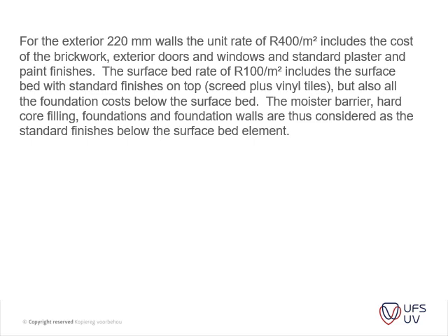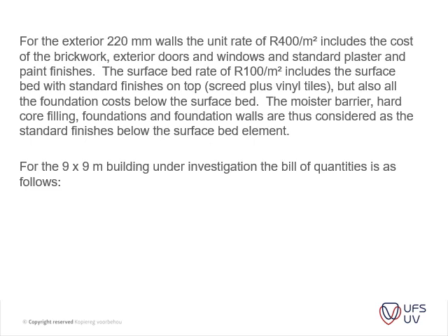The moisture barrier, hardcore filling, foundations and the foundation walls are thus considered as the standard finishes below the surface bed element. Okay. For the 9 by 9 meter building under investigation, the bill of quantities, which I will not actually say is a bill of quantities, but more a schedule of quantities, is as follows.